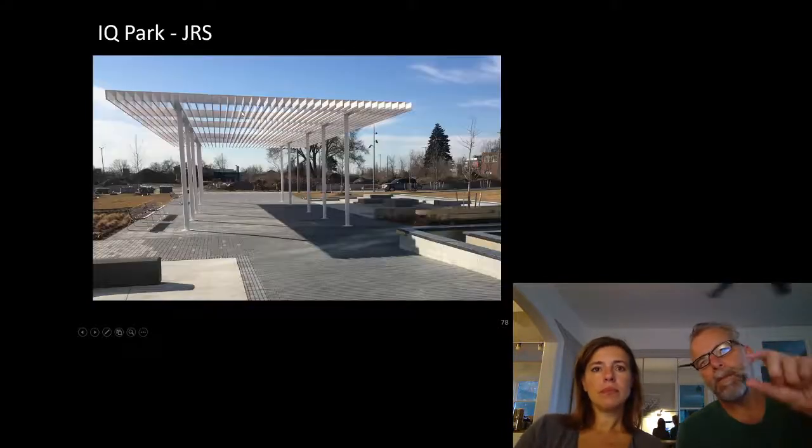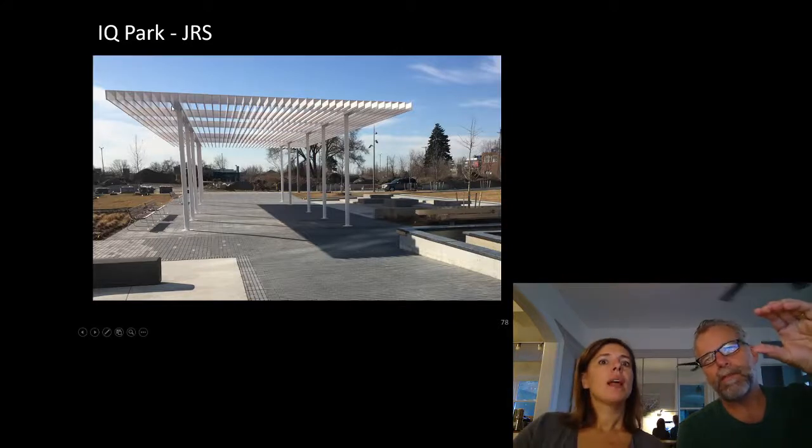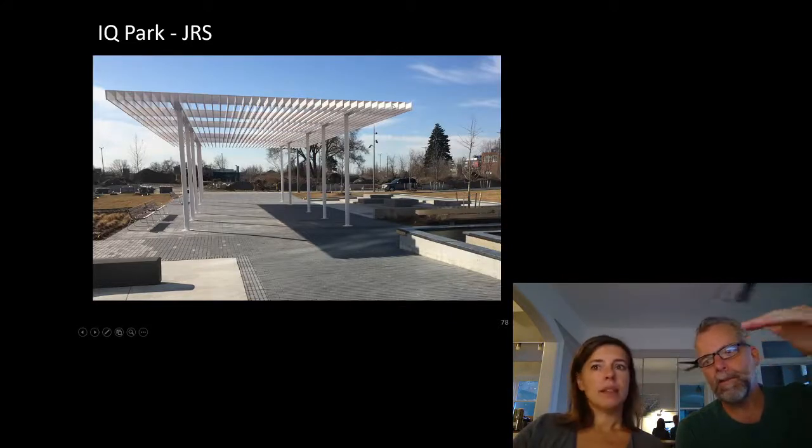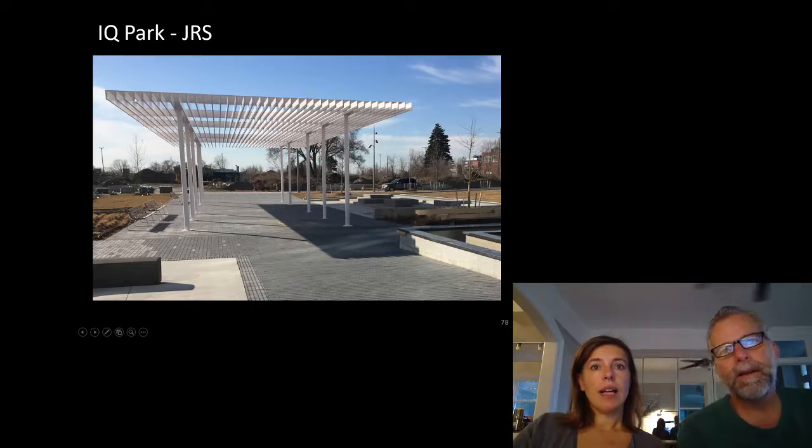This is a good example where the projected profile is very thin, so it would pick up very little wind, and so you would design for friction on the surface, right? I wanted to be really conservative with this because it was kind of a unique thin structure that I did projection.